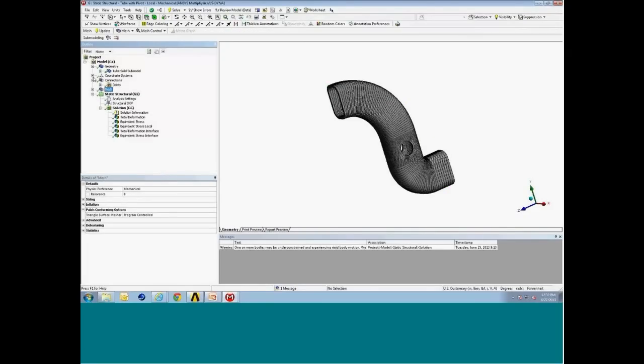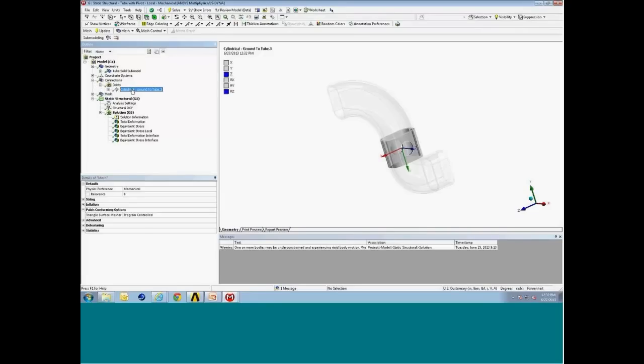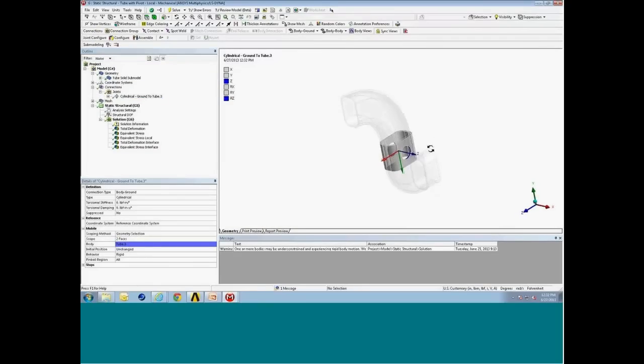So with this, I just want to show you the cylindrical joint we included on the solid model as part of the analysis, since this was interior in this local model, which was also included in the global model. So that is also included. Now, the whole challenge in running these submodels is transferring the boundary conditions from the global model, especially when you have some perhaps arbitrary cross-sections or arbitrary locations. You want to take a slice and really transfer those boundary conditions.